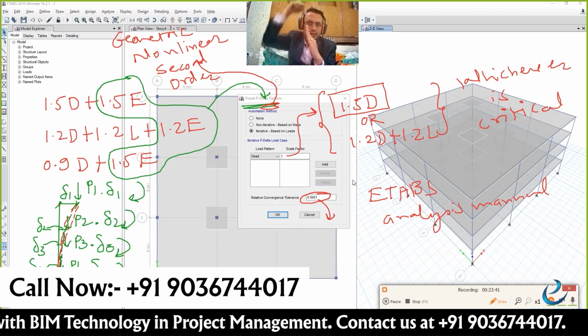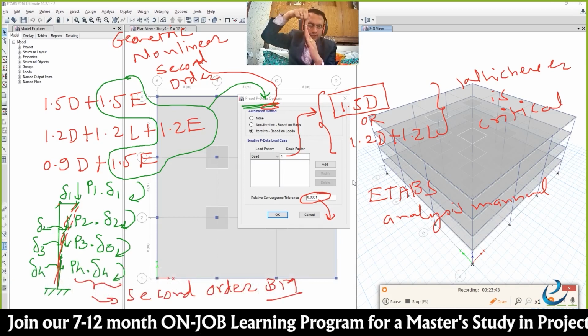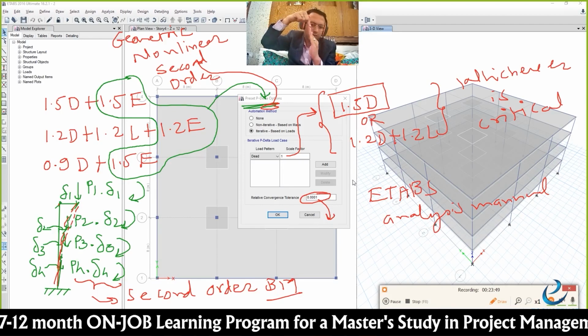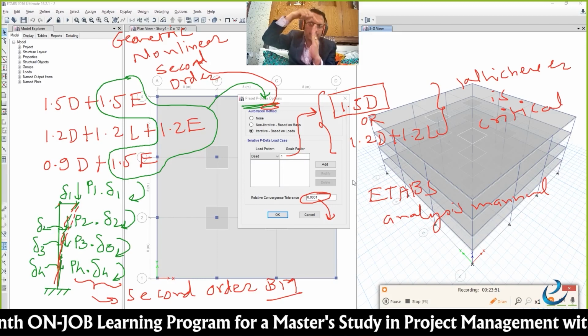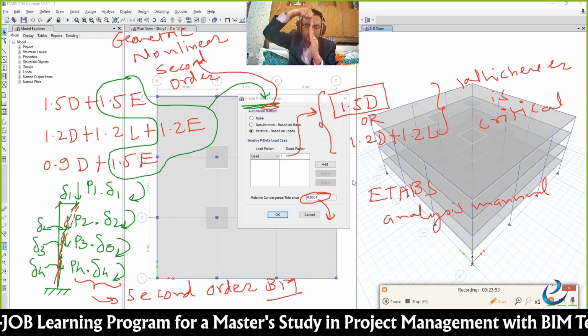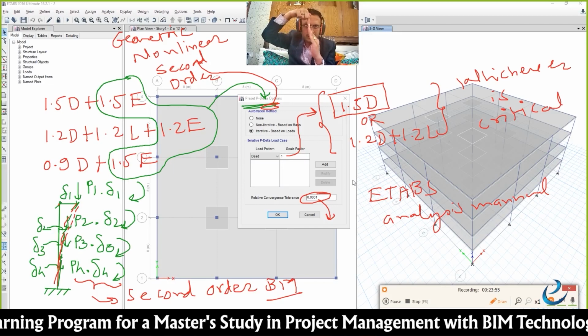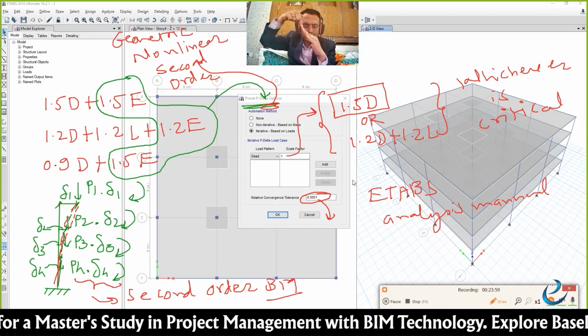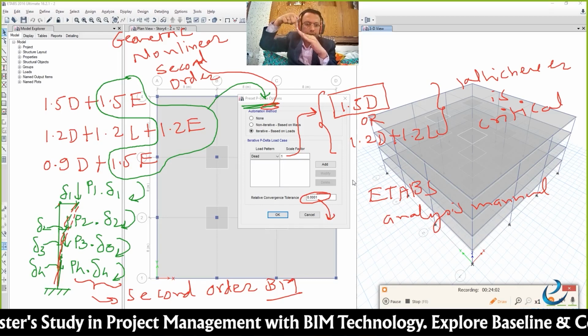But the self-weight of the column is there. Vertical force of the column is also there, right? Because of that, this particular bending moment may occur. So by default, there is a P into delta. Because of this delta, again there will be the second order delta, then third order delta, then fourth order delta, then fifth order delta, like that.